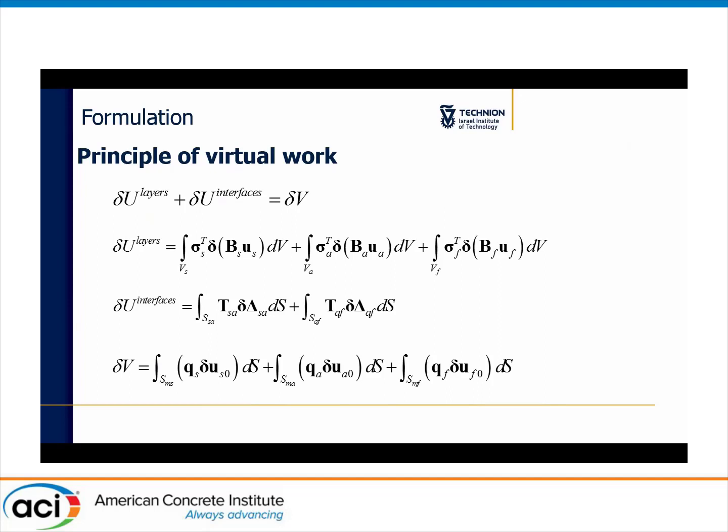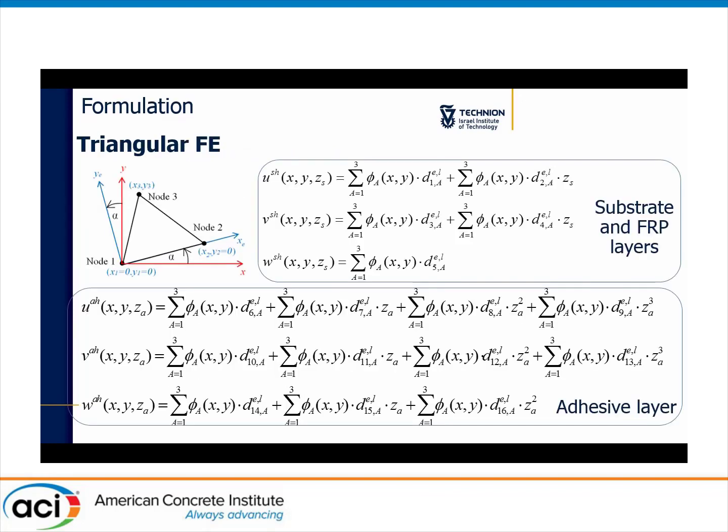A principle of virtual work concludes the formulation of the model and is the basis for the two-dimensional multi-layered plate element used in this study. We used a linear triangular element which enables us to deal with the geometric irregularity which is inherent in the problem at hand.